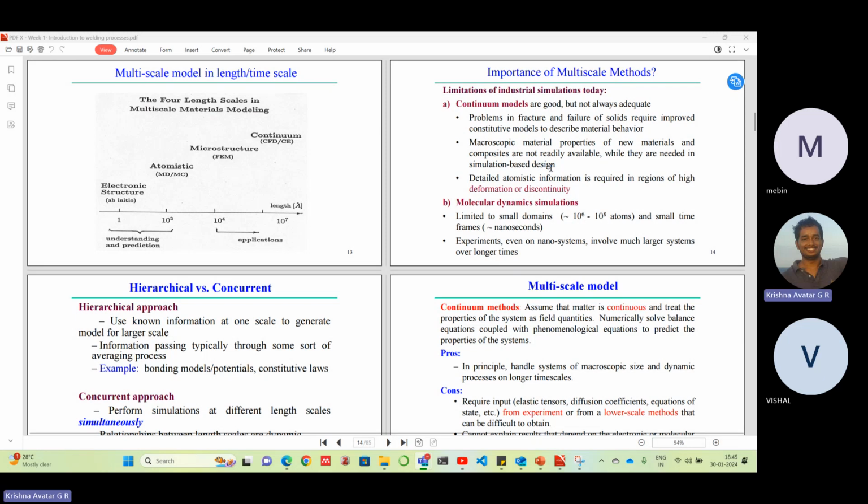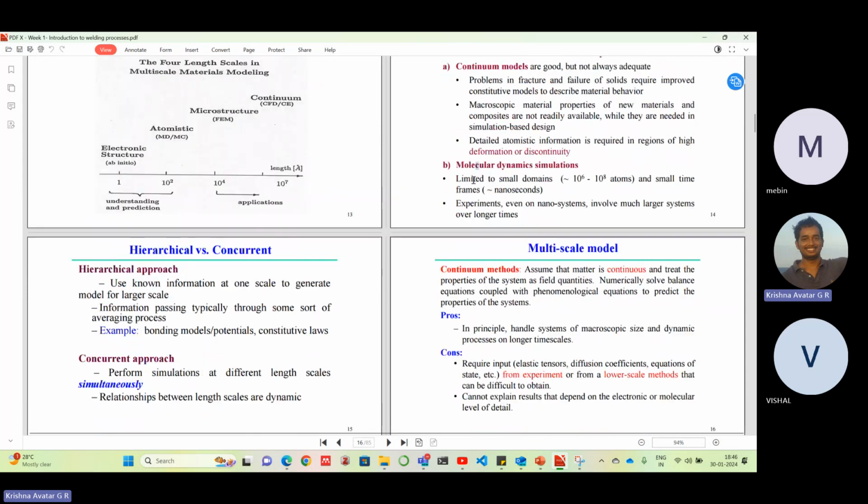The peridynamics method is able to even model a discontinuous system, since it does not actually take into account the derivatives of the displacement at every point. If the body happens to be discontinuous, then the derivatives cannot be defined, isn't it? So that is a subject of another study. I just wanted to introduce it here.